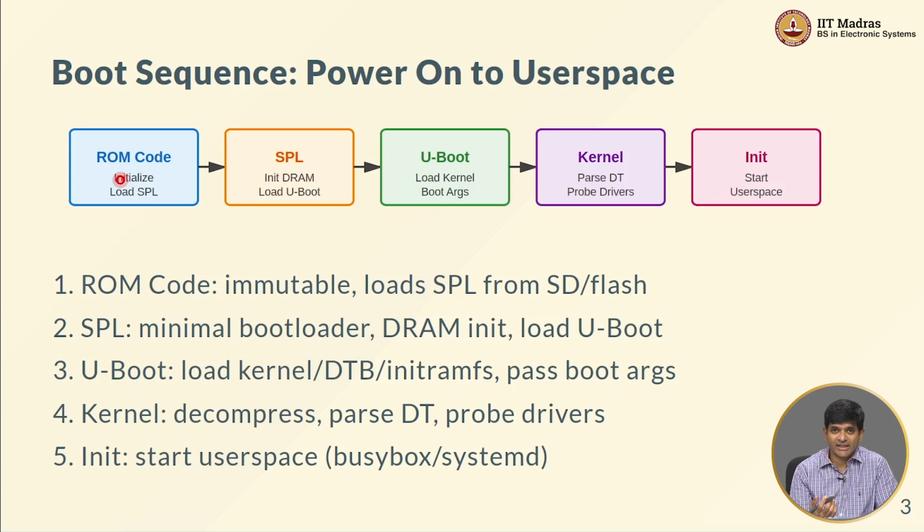Nowadays even power management ICs, because power is ultimately what you would think of as an analog domain circuit, but the power management ICs have fairly sophisticated digital control. They can be programmed to generate different kinds of voltages, they can be programmed to different current settings and so on. So that the PMIC or power management IC needs to be brought up in a certain way, which means that I need to be able to do that kind of programming and at least initialize it, right. Similarly, maybe for the PLLs to just get some clocks going and so on, but very basic, and its main job is to load something else called a secondary program loader, or the SPL. Now this SPL is what we call a very minimal kind of a bootloader, right.